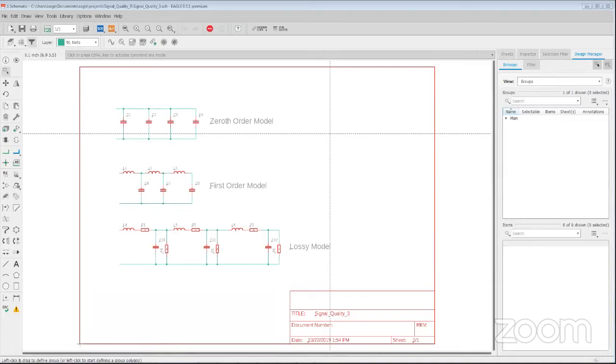You can use these capacitors to establish a characteristic impedance for the line. Now, obviously, in most real world cases, you wouldn't be able to measure that. It would happen so quickly, and because the other end of the transmission line is open, it would just read open as soon as you could get a probe to it. But imagine that you had a transmission line that went from the Earth to the Moon, about 240,000 miles, total round trip, okay?